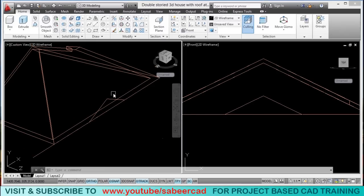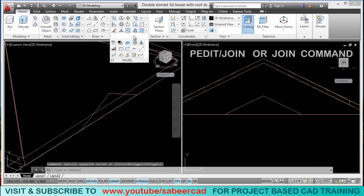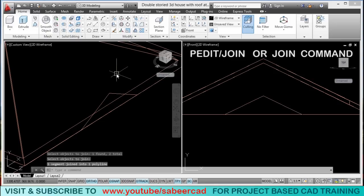Next, I'll convert these 2 segments as a single profile. For that, I'll go to Modify panel and I'll select Join, or else you can give the Join command and I'll select this and this as the object to join. And when you right click, you can see that these 2 objects will get joined as a single object.